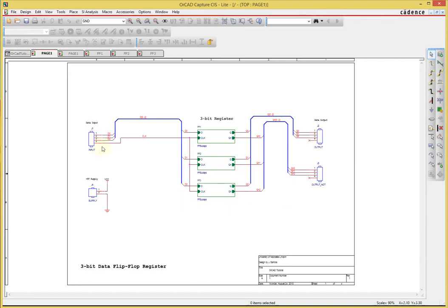And I think I'm done. So I have all of my parts. All the parts have reference designators. All of the reference designators are unique among my occurrences. I did the DRC check, it passed, and I did a footprint for all the parts, and it's good.